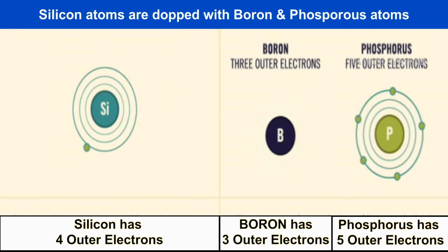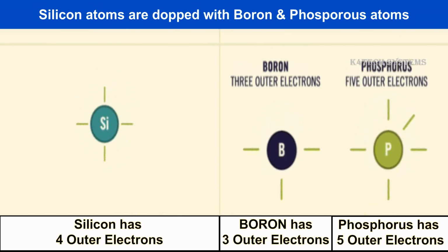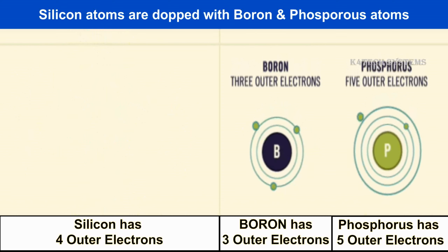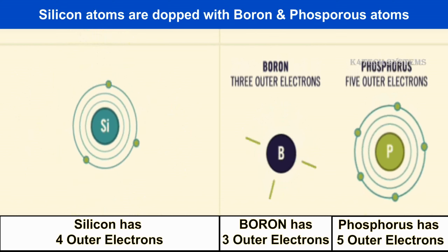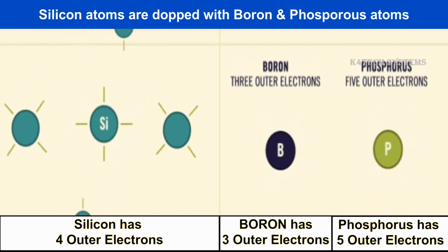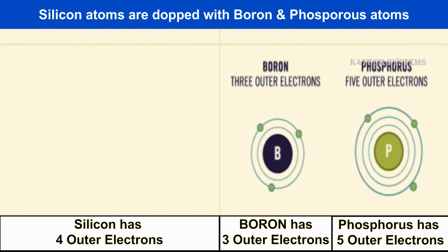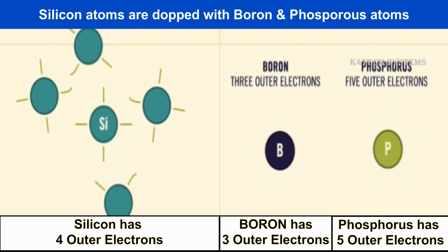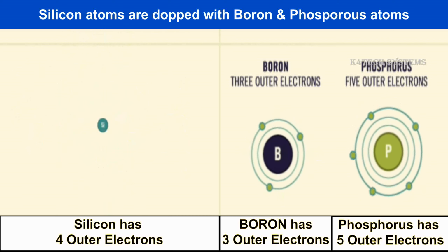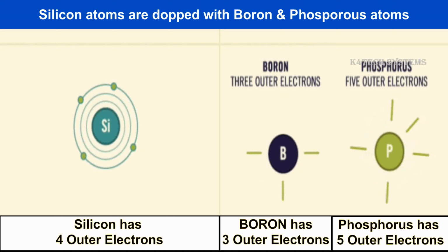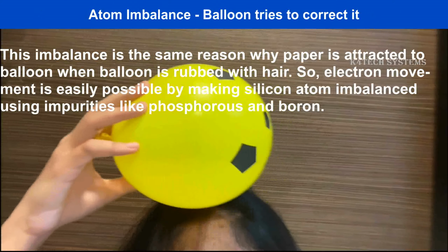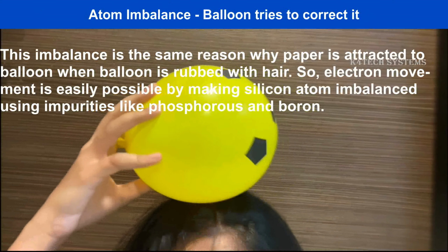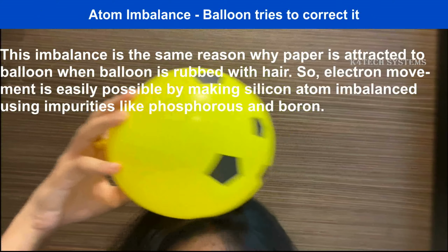Doping of silicon with phosphorus and boron elements. In the silicon atom there are 4 valence electrons that can be shared with the other atom. In the boron atom it is 3 and in the phosphorus atom it is 5 electrons. Electricity is produced in solar panels by creating an imbalance in each atom by mixing these 3 elements. This imbalance is according to the reduction or addition of electrons or holes in mixing while doping.